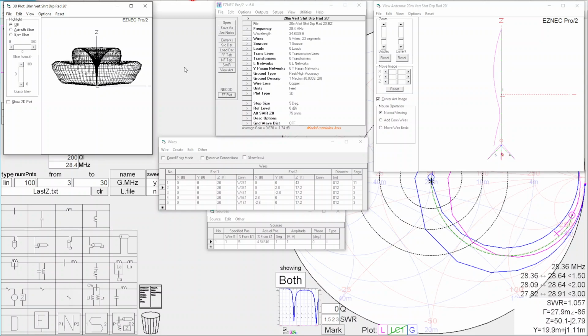And at that point, I have a pretty good idea I'm going to be in shooting range of having a working antenna. All I have to do is do a little physical tuning, and then I take a NanoVNA scan, capture the S1P file, drag and drop it into SimSmith, and see what the actual antenna is actually doing.